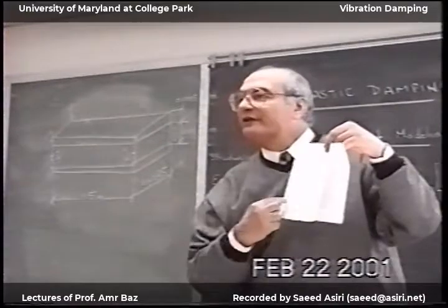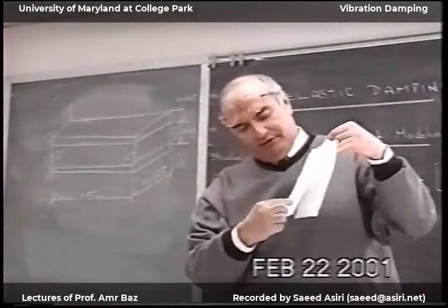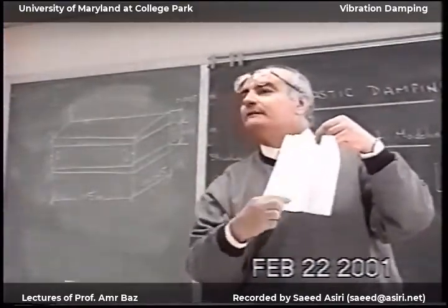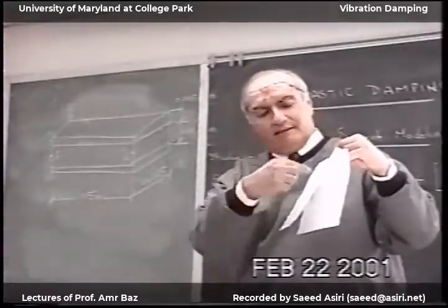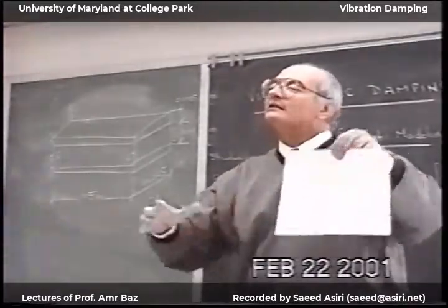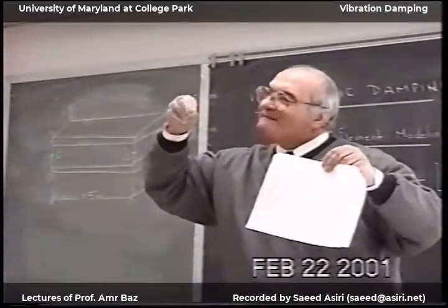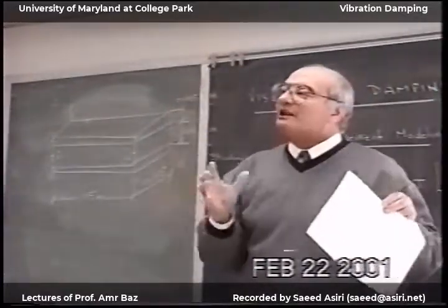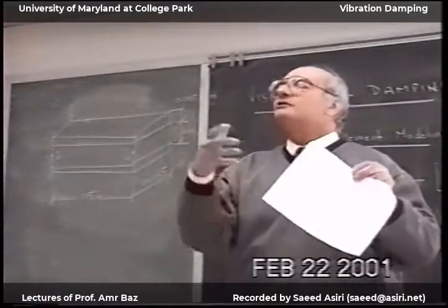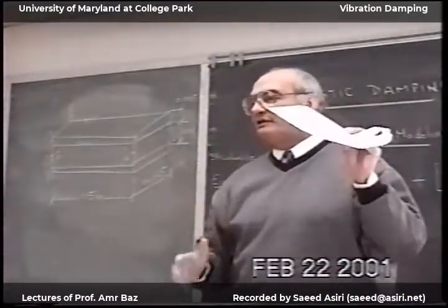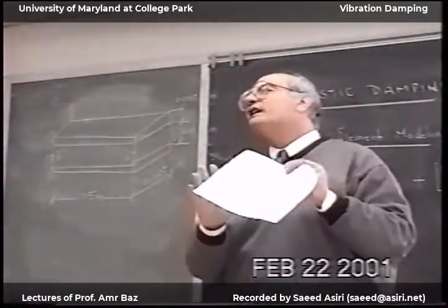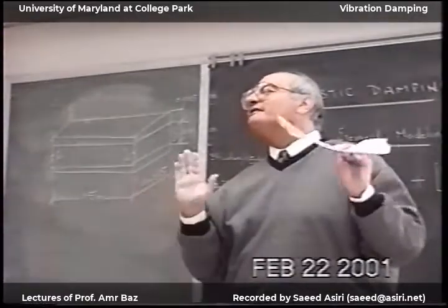As function of temperature and as function of frequency. So you take this and then divide it into a grid. Enlarge it so your eyes will not hurt. And then pick points and generate tables like what I did. And then we want to do master graphs for this material. Once you've done this once, it'll never go away from your head.